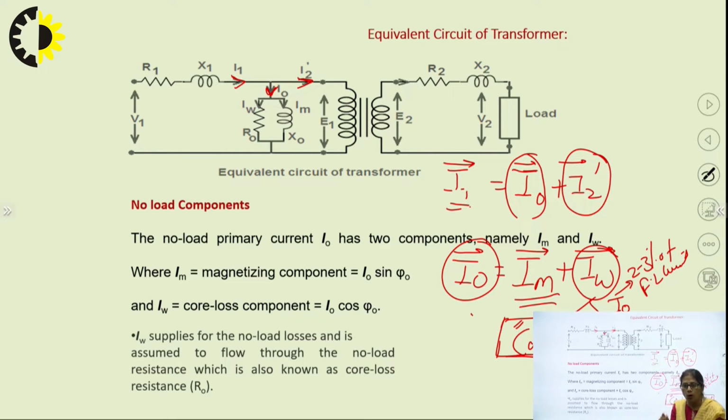With that much small current, the losses occurring because of it are I0 squared R losses at no load condition. The resistance is very small as it is, and the current is also very small at no load condition. So the copper losses would be comparatively very much smaller and we can neglect them.